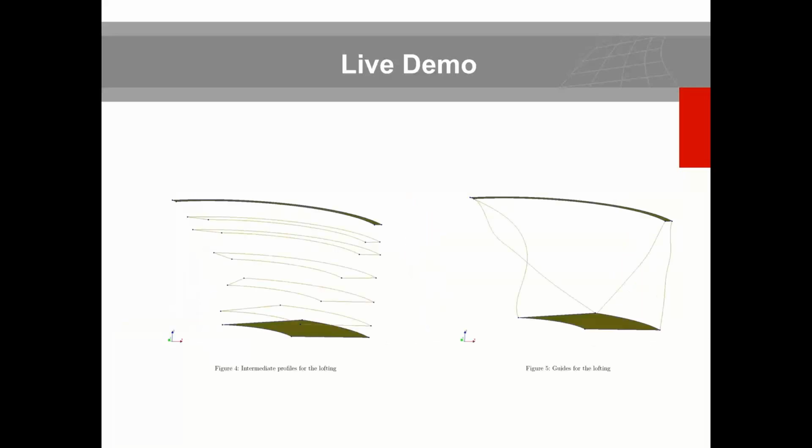To make the geometry of the dam with the lofting operation, we will consider two options. One using intermediate profiles, so all these profiles. So we will start by creating a curved line for the upstream and downstream and create a closed wire. And for the second one, we will just use curved edges to define the trajectory, and we will just create the crest and base sections. So let's move to Diana.